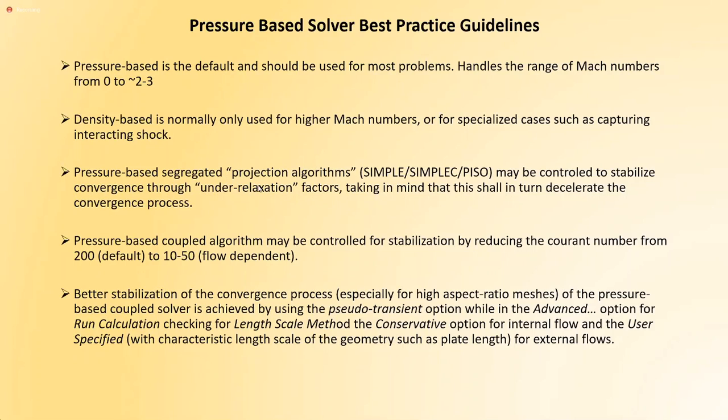Pressure-based segregated projection algorithms. You have my posts about projection methods. SIMPLE, corrected, PISO, maybe controlled to stabilize convergence through under relaxation factors. Again, did anyone not understand what under relaxation factor is? It's like, I have to walk from the beginning of the room to the end of the room, and instead of taking 10 steps, every step I take half a step.